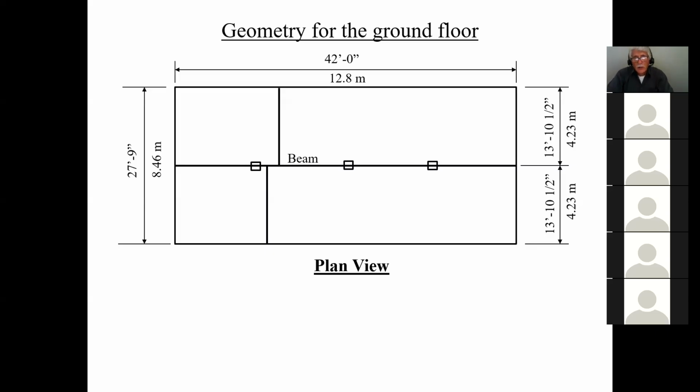So right now, I'm going to look at this 42-foot one and say, well, I'll put a column there, a column there, a column there. That is, if the architect doesn't mind having 3 columns in his basement because he's not planning to finish the basement anyways. And therefore, by having the spans up to 12 feet, I will end up with a reasonable sized beam here, okay? So that's how I work it out.